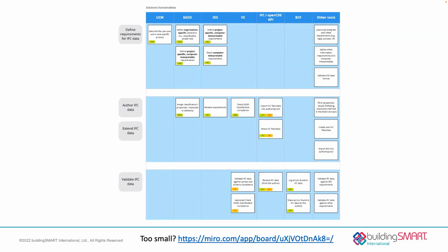I'm curious what the outcome will be, but yes. So you can say, I need a B-rep in here, and then the file needs to have it, but there's no further way to say, well, at least these kinds of angles or whatever. That is what the CEN standard, level of information need, is trying to do. We try to focus on this first step first, and then the CEN working group is trying to figure out how you should do requirements for geometry, following that development and following up on new versions. With this very bare minimum.